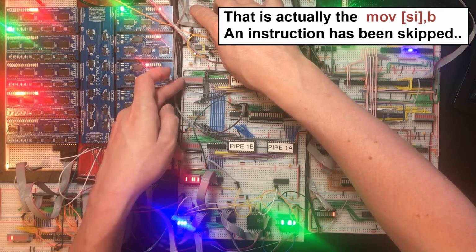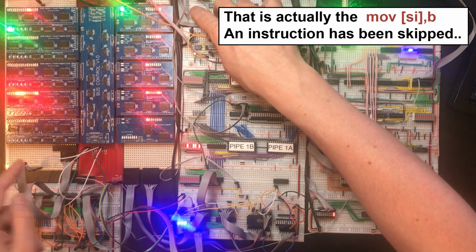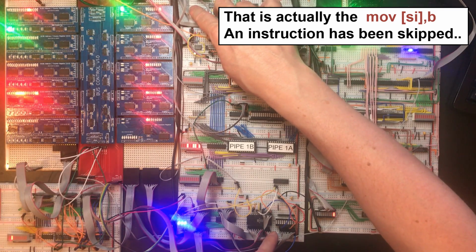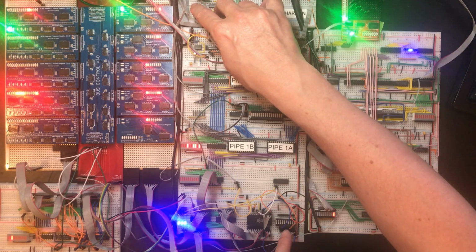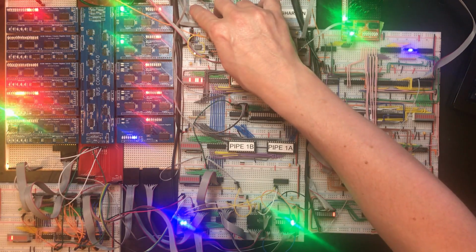I won't do anything till it gets to here, but A is 1 and the address of TX is 128. So if it works, we'll just see the lower LED. If it doesn't work at all, we'll see the upper LED because it's the 128 that's being read. And if we see them both come on, we turn it all off quickly before something dies.